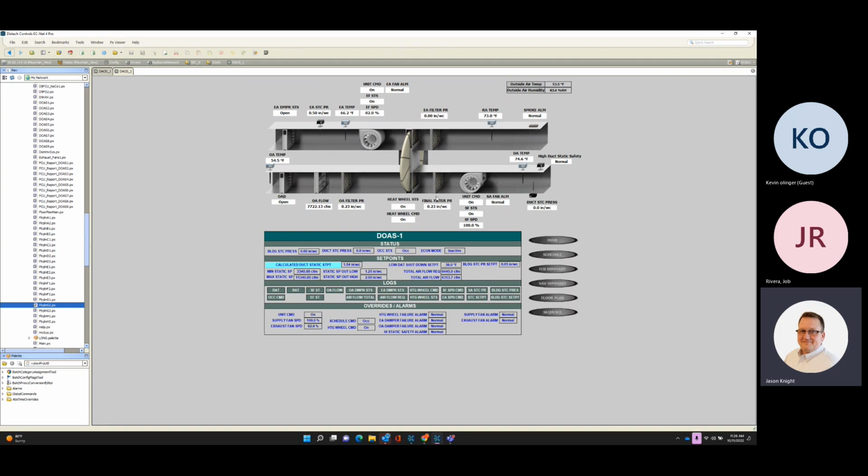The balancer went through, balanced all the ductwork, measured the total airflow coming out of the fan coil, how much chill water was going through the chill water coil, and then gave us the speed that was initially determined by the engineer. So those high, medium, and low speeds we put in for cooling, heating, and whenever the unit was satisfied. If it was in between set point, it would just go to a ventilation speed. The ventilation speed we'll talk about later.